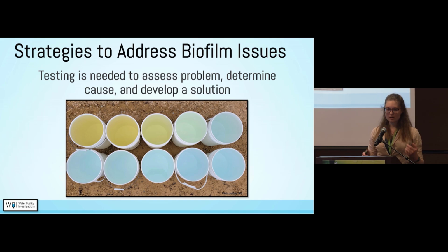You would guess that water would look the same from a well, as long as it's the same well and pumping rate and whatnot. But what we found in this instance is that the upper portion of the well, probably in the cased region, that'd be about the first 4 minutes of pumping, was creating some corrosion issues, and that was causing the discoloration that this homeowner was experiencing.